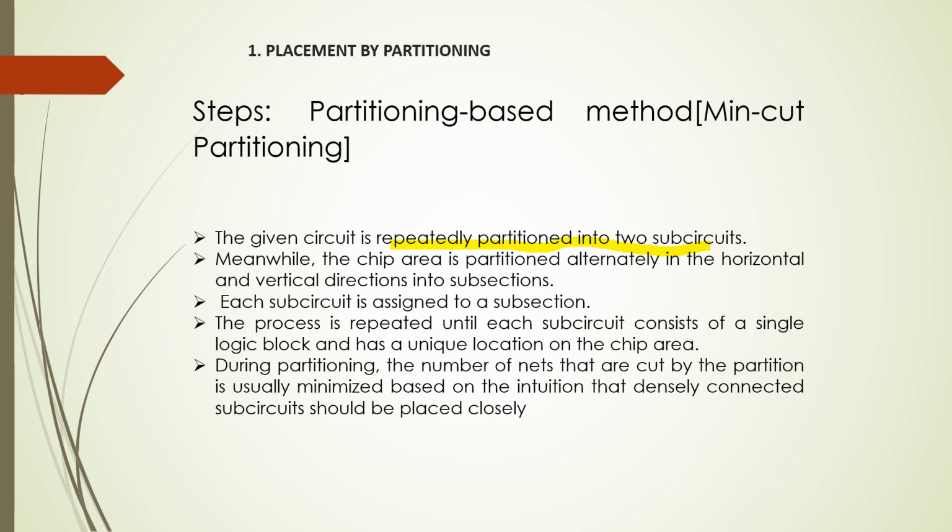the first thing is we partition the circuit, the whole circuit, into different sub-circuits. So the chip area is partitioned accordingly. So we divide the whole chip into vertical and horizontal subsections and then segment it, and then each subcircuit is assigned to a subsection.